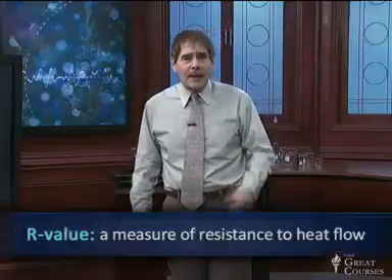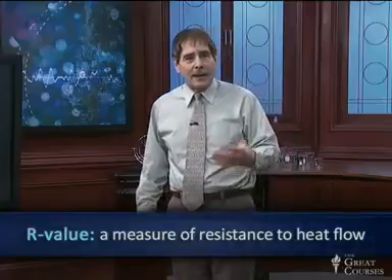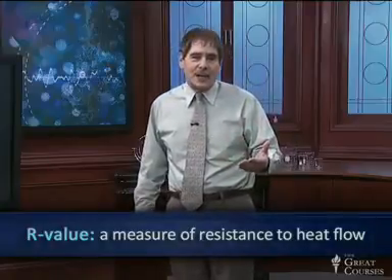One way we express the process of heat conduction, particularly in building materials, and talking about building houses and building energy-efficient houses and so on, in the United States particularly, is with something called R value. Well, we have R value in other countries, but it's expressed in different units. In the U.S., it's in English units. And the R value measures the resistance to the flow of heat of a material. Its units, we almost never say its units. We say this thing has R10 or this thing has R20. It does have units, but it's much easier to understand the inverse of the R value.